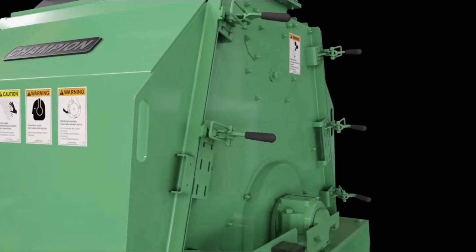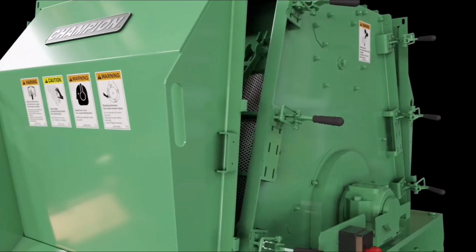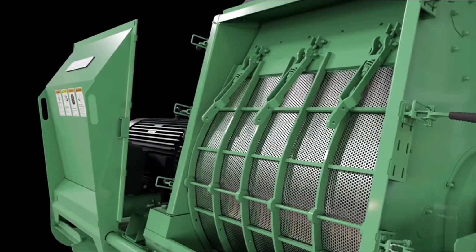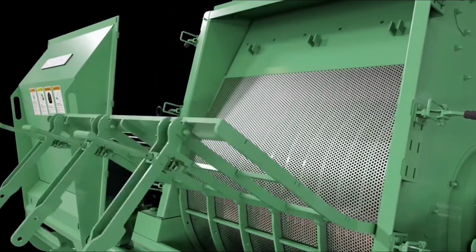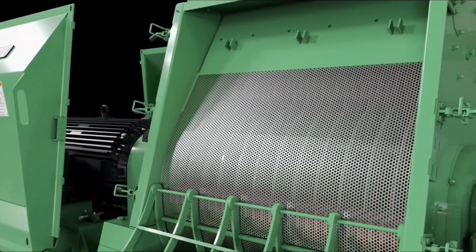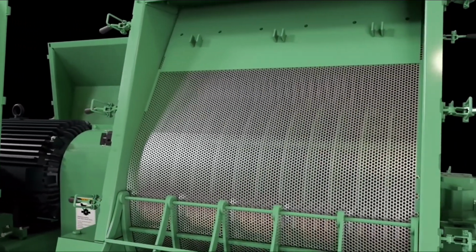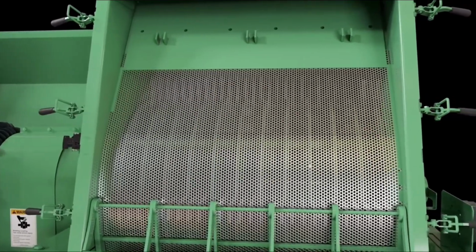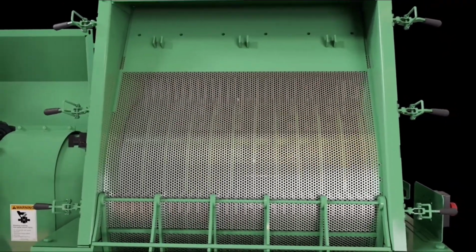Material is crushed in two stages: size reduction, which occurs by dynamic impact, and sizing, which occurs by attrition and shear in the second zone, where there is a small clearance between the hammer and the screen bar, resulting in a particle range of 15 to 50 micrometers.